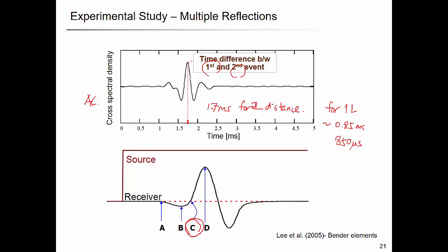So actually, different groups have different methods, their own methods. I think in the soil dynamics lab they use square and sine waves at different frequencies, and they just determine the arrival time from the different signal arrivals.